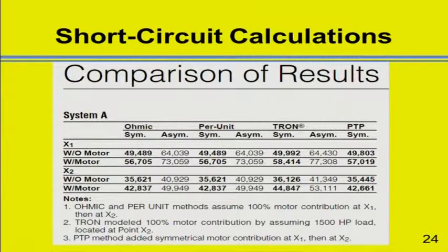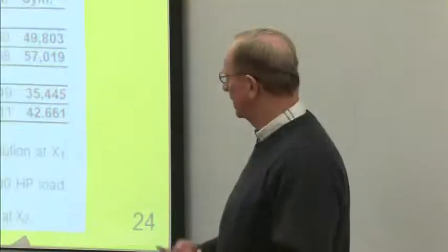It's generally used to size equipment. It can be done in the field, really, when someone's working on a piece of equipment trying to come up with an idea of why this needs to have better protection or why it didn't have the right amount of protection. It allows you to get a quick answer for that kind of a question. So short circuit computer programs are available to do that, but like I said, you can go online and do it for free, so why would most people buy the computer program anymore?